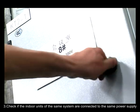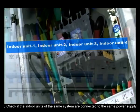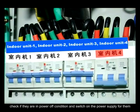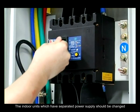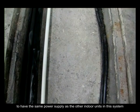3. Check if the indoor units of the same system are connected to the same power supply. If some indoor units have separate power supply, check if they are in power off condition and switch on the power supply for them. The power supply of the system must be modified later. The indoor units which have separate power supply should be changed to have the same power supply as the other indoor units in this system.